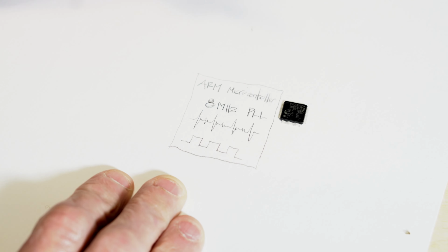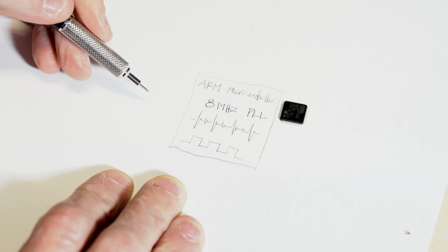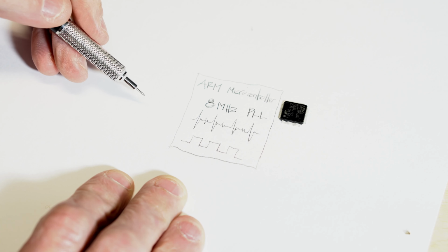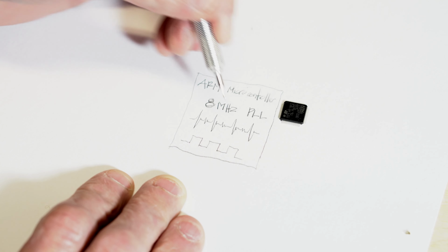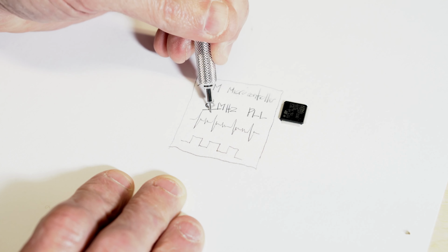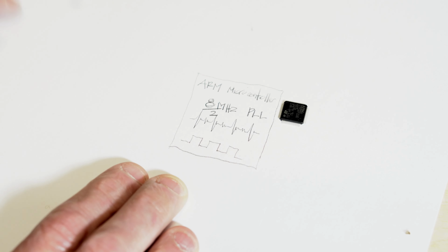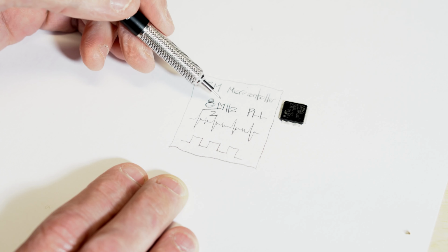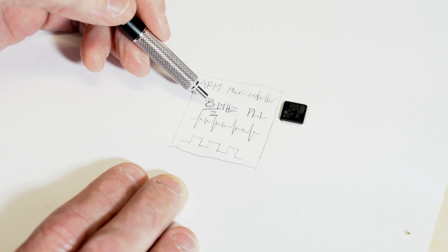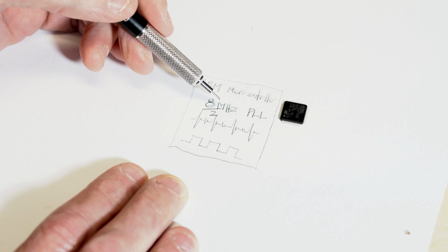And all you need to know is that this PLL allows the internal clock, the HSI, to be multiplied. But it's multiplied by this speed divided by 2, which is 4 MHz. So let's go ahead and try this out and see what we can do with this internal HSI, and how we can make the clock speed faster using the PLL.